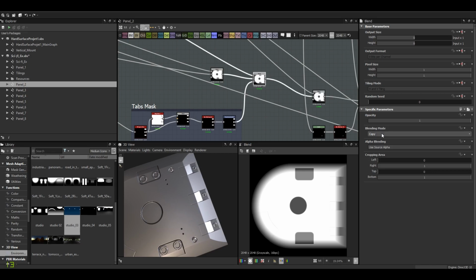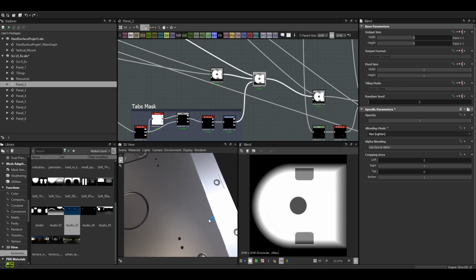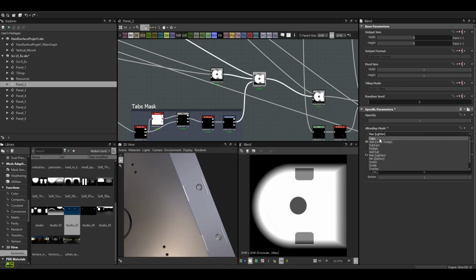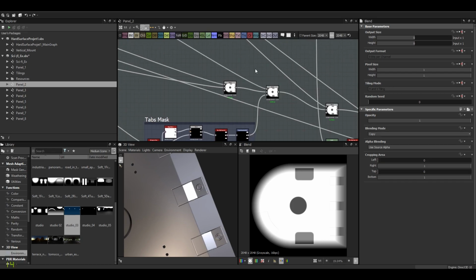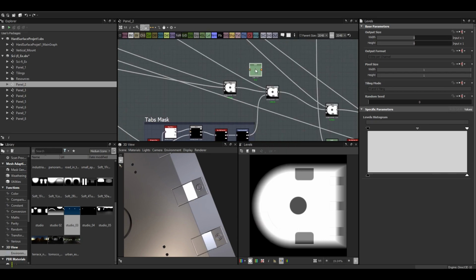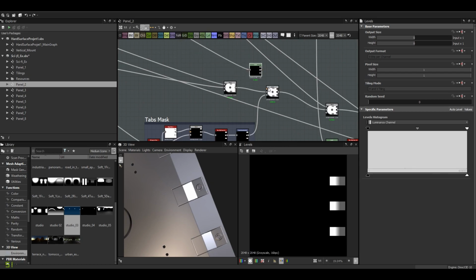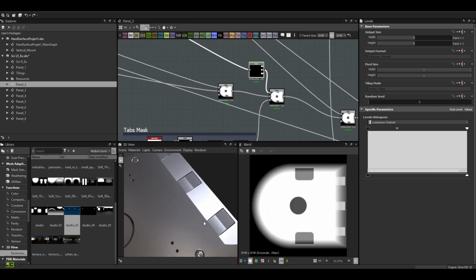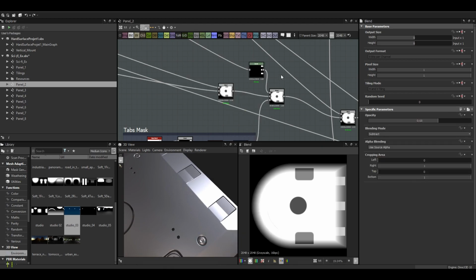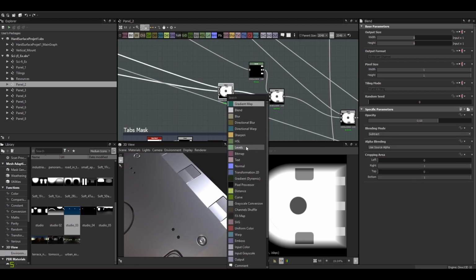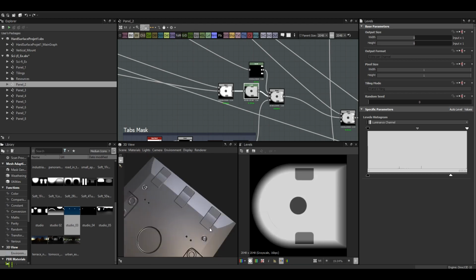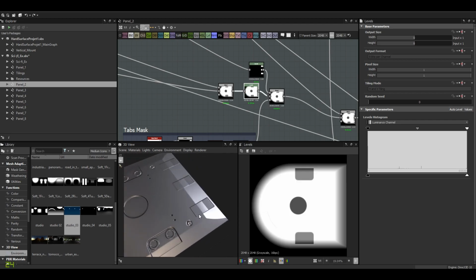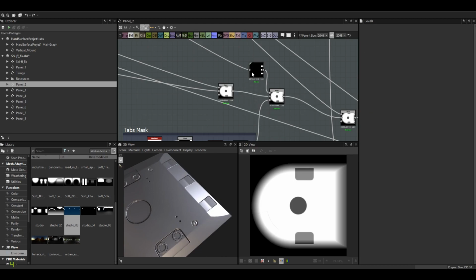If you use the max lighten in such a case, you'll get almost nothing, as you can see. Even by using a levels node to correct the values, we don't get exactly what we need. So the best course of action here is to use a mask.